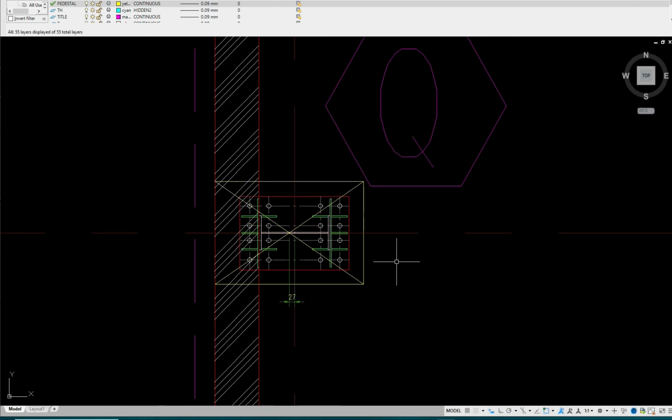This way we should locate the distance between the CG of the columns and the CG of the pedestal at all locations, and thereafter only we should proceed for STAAD Pro modeling of foundation.